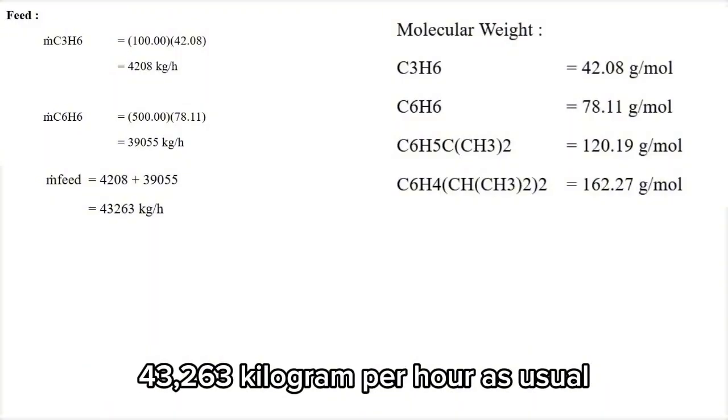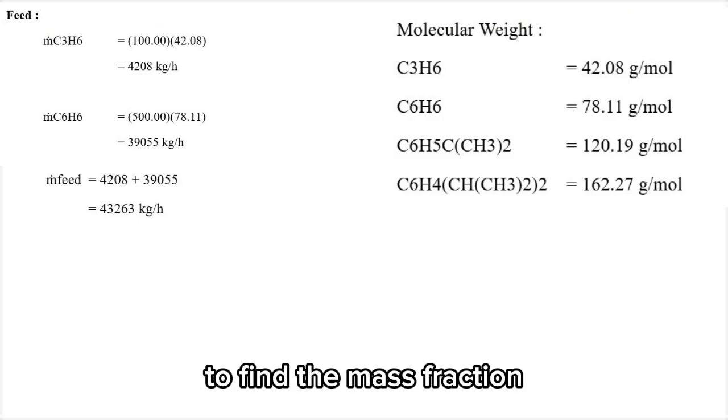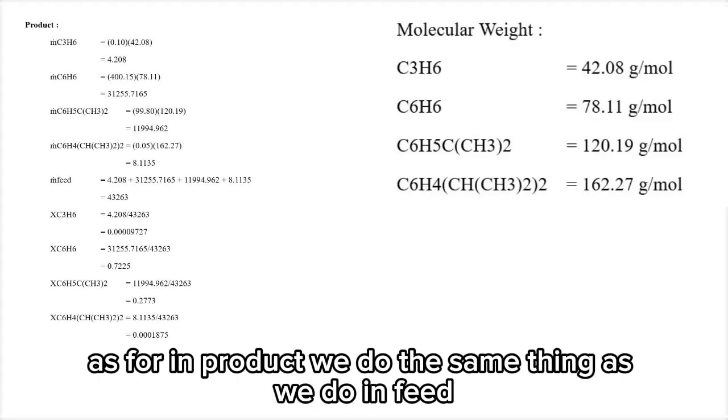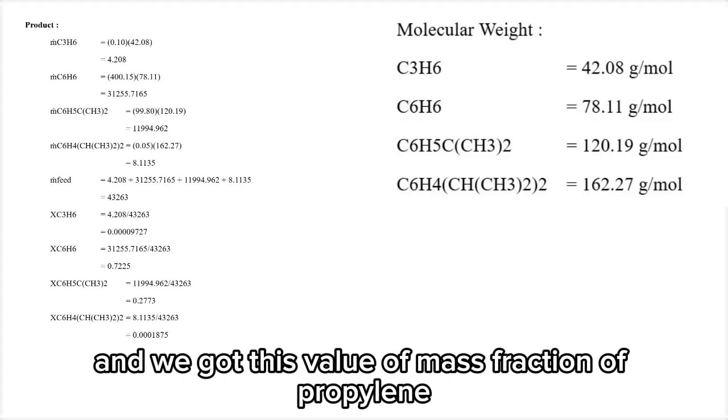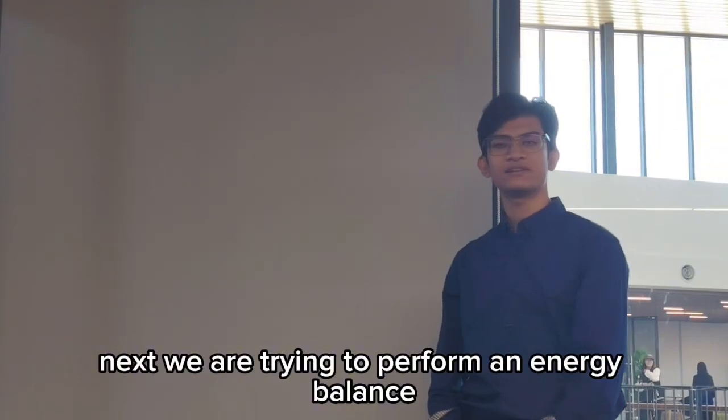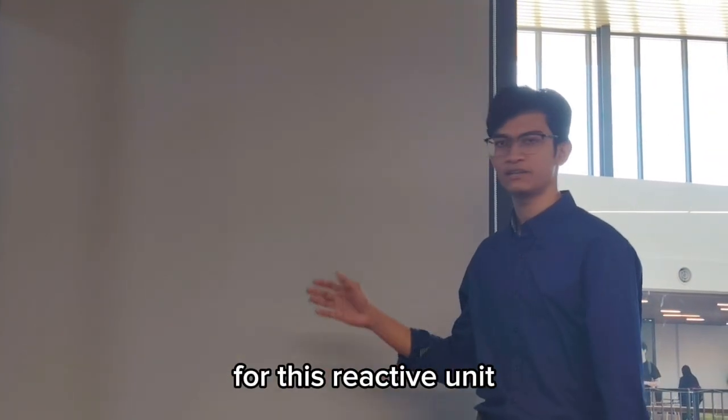Then we should find the mass flow rate of feed, 43,263 kg per hour. As usual, to find the mass fraction, we should divide the mass flow rate by its total mass flow rate. As for in product, we do the same thing as we do in feed, and we got this value of mass fraction of propylene, benzene, cumene, and diisopropylbenzene. Next, we are trying to perform an energy balance for this reactor.